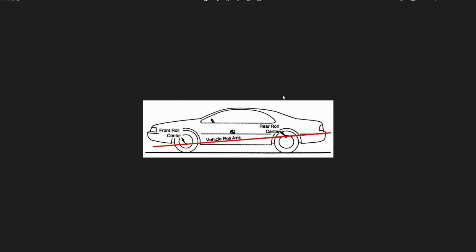Then as you get in the corner, the front left and right tires are more equally loaded at this point. You have good grip mid-corner. So the front wants to turn the car. Now on the rear, you have the higher roll center, more geometric roll stiffness, which means that mid-corner, the outside tire is heavily loaded, inside less, which means you have less rear grip in the corner, which means that the rear allows the car to turn. It's not gripping too much. So in an extreme case, if you angle this very much, you go in good, and then mid-corner the rear wants to slide. Right?